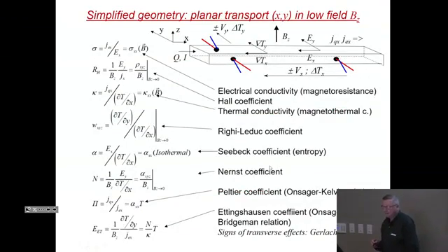Okay, so this is the simplified summary of it all. You have the voltage and the thermocouple probes here. You have the transverse voltage or thermocouple probes. And then what you have is, every time, a measurement of a temperature difference, delta T, which you have to convert to grad T by dividing it by the length between the contacts. The same when you do an electric field, so red wire to red wire, for instance here, copper to copper, or a longitudinal electric field, copper to copper.